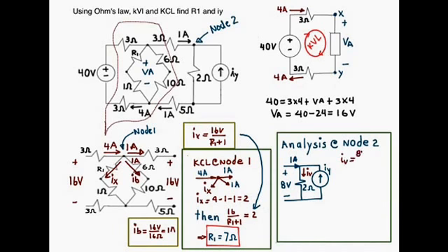So if we write current I sub b as the current going through the 2 ohm resistor, we find that that current is equal to 4 amps. Now Kirchhoff's current law at node number 2 is 1 amp plus I sub y plus I sub b is going to be equal to 4 minus 1. I sub y must be equal to 3 amps in order to make that current I sub b equal 4, and 4 times 2 equals 8 volts. And that's the solution to this problem.